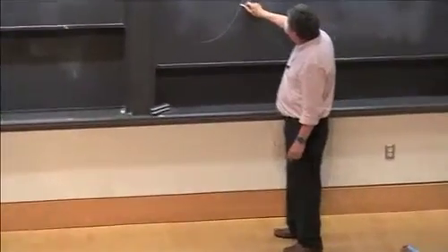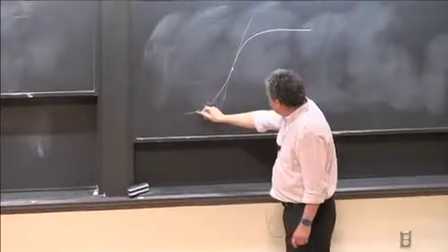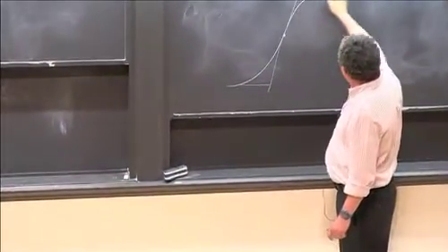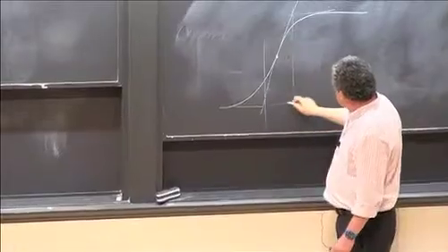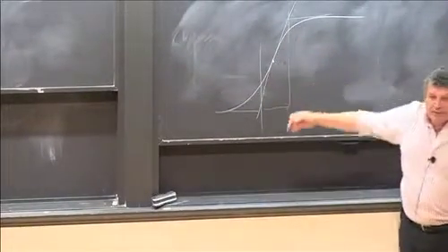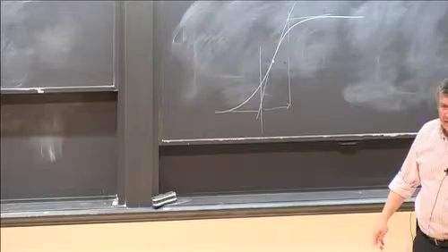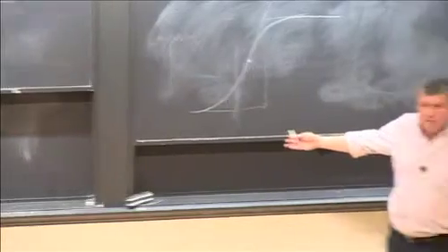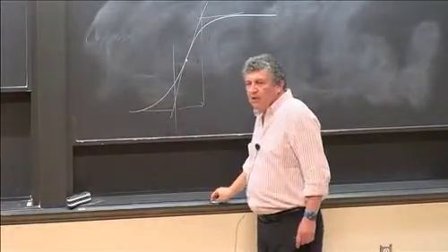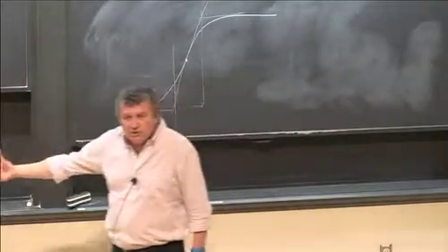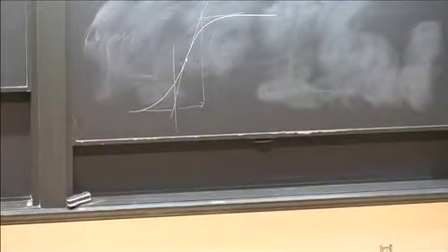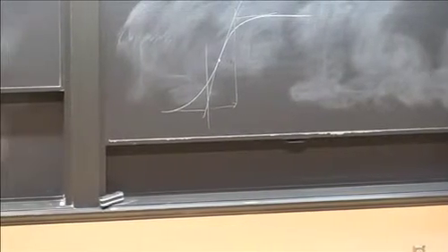For example, you take the inflection point and you define the flame thickness to be a region, say, between when that hits the asymptote or something like that. Well, there is an arbitrariness here as well, okay? And it's not clear how much of the full reaction zone that catches, okay? So you have to define it in a certain way. By the way, in boundary layer theories in fluid mechanics, you also define the thickness of the boundary layer in a certain way, and you have to make a choice how you define it. So it's the same idea.